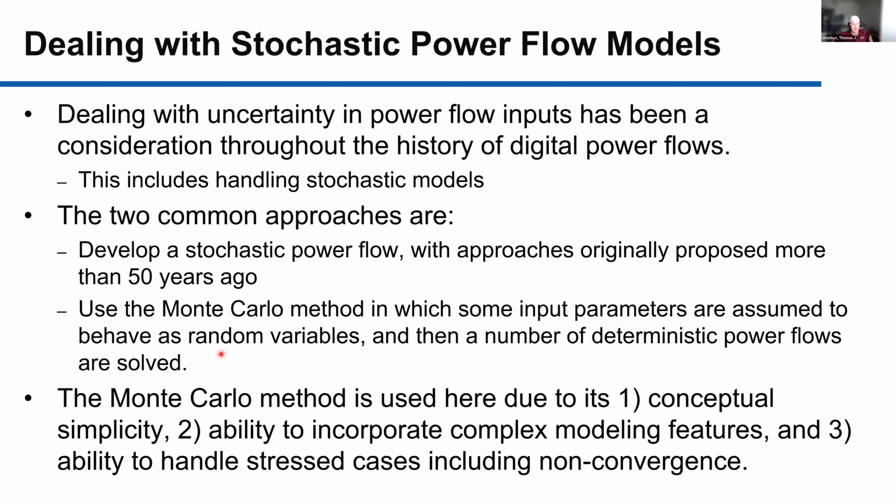The Monte Carlo approach is where you just do a whole bunch of deterministic power flows. In implementing this, we decided that we would handle stochastic PFW models using the Monte Carlo approach. The reasons were, one, it's got good conceptual simplicity. Two, it's able to incorporate complex modeling features. And three, its ability to handle stress cases, including non-convergence.